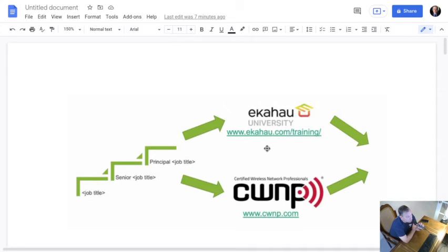And then you could choose what model of AP you're going to be installing and drag them out onto the floor plan, and Ekahau will automatically predict the coverage of a given area. That way a wireless network designer can recommend locations for access points to be mounted.